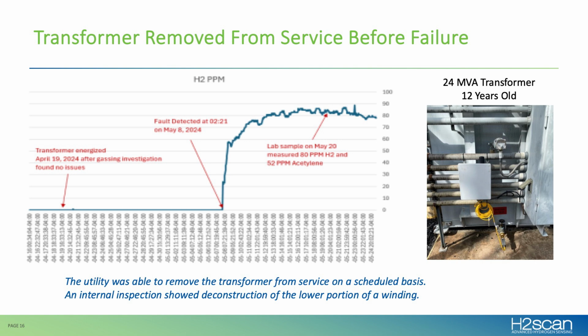They actually had taken the transformer out of service and degassed the oil. They couldn't find any problems and put it back in service. So it shows there April 19th: the transformer was energized after gassing investigation found no issues. They couldn't find any issues with the transformer.